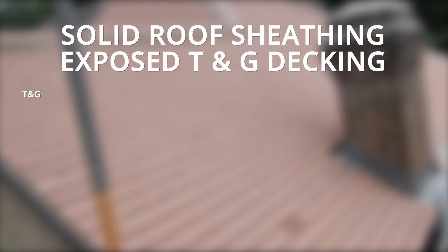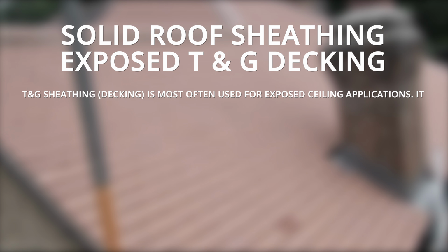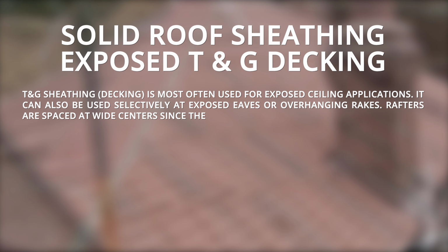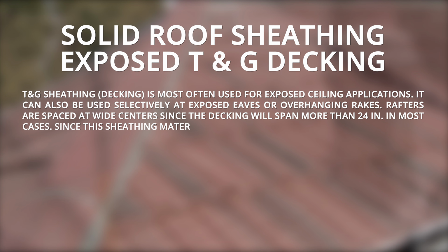Solid roof sheathing, exposed T&G decking. T&G sheathing, decking, is also used for exposed ceiling applications. It can be used selectively at exposed eaves or overhanging rakes. Rafters are spaced at wide centers since the decking will span more than 24 inches in most cases.